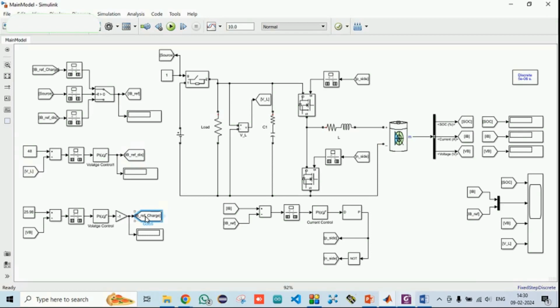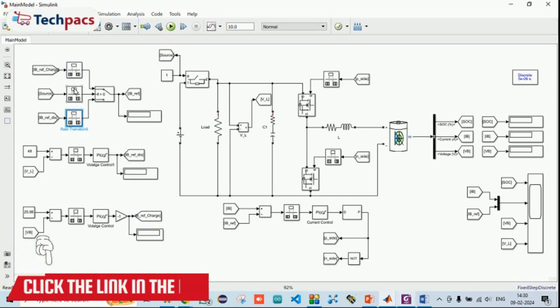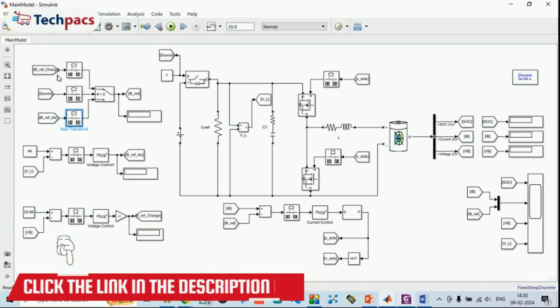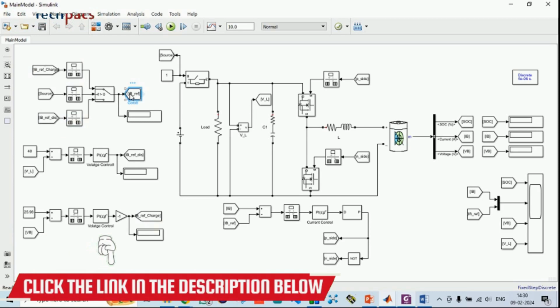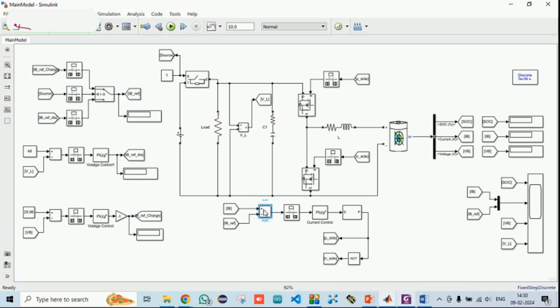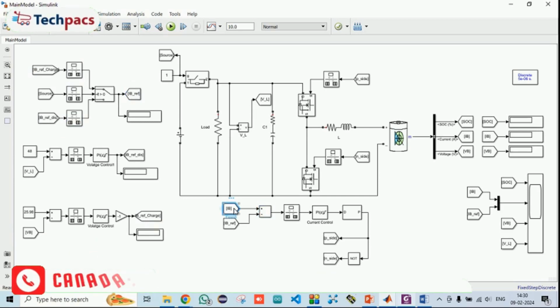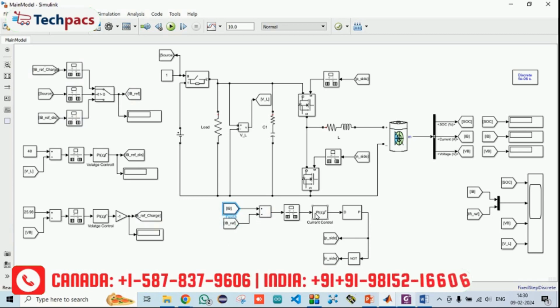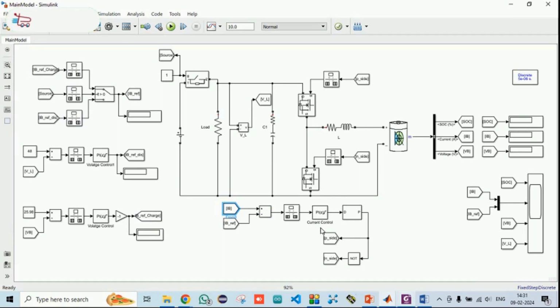These two inputs are given to this model, where it checks whether there is a source flag, charging flag or discharging flag. On that basis, that particular value is sent to the model, which is compared with the actual input we are getting at the system. Comparing these two, we get a decision for generating the duty cycle, in which we are using the PI controller to decide that.